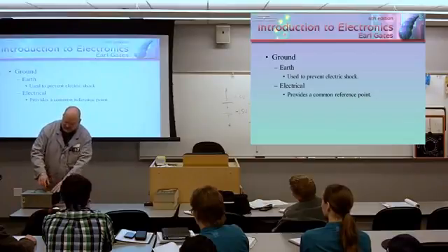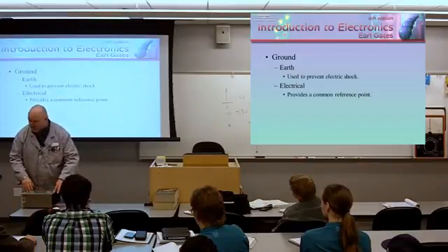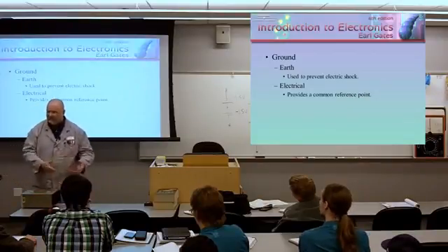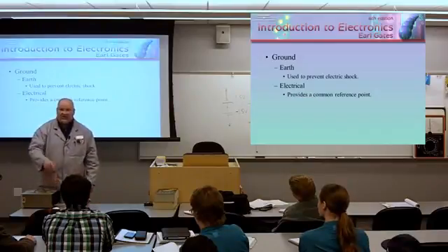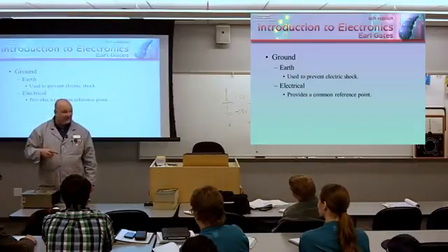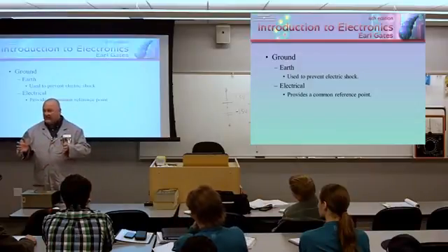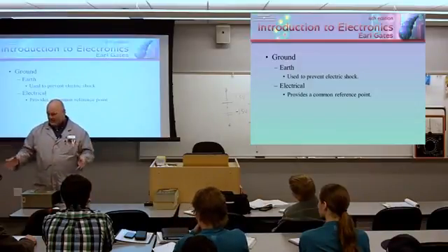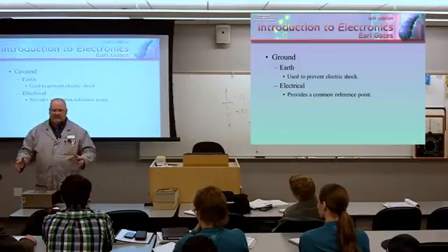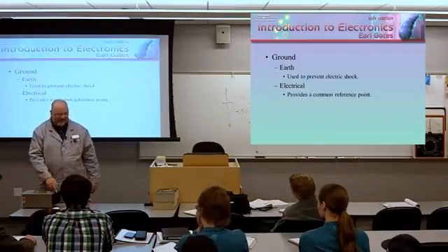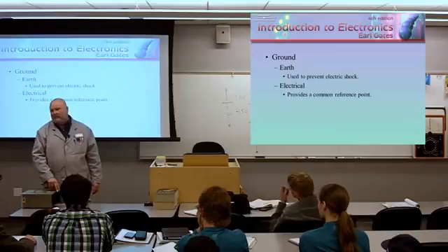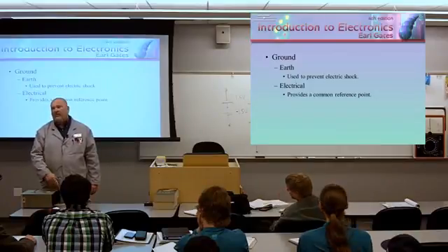This, in some cases, could be electrically isolated from ground. This could be connected to some big high-power transmitter tube for the purpose of dissipating energy, and it could have, like that mica that I passed around earlier, a big sheet of that mica there electrically insulating it from the rest of the chassis or frame of the piece of equipment. And that's taken out many a good technician. So never assume. Never assume.